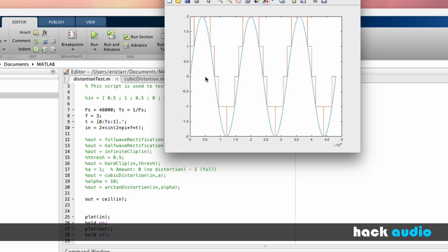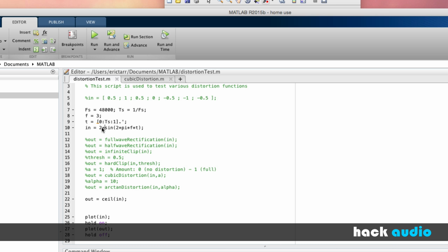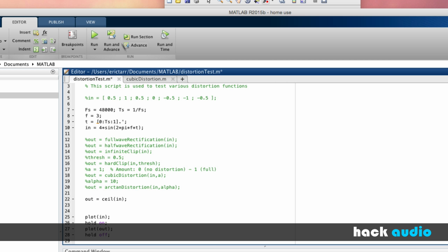Now, because we're working with signals that are stretched over a larger range, over a range of -2 up to +2, that's over 4 integers there, the number of bits is going to be 2. So we're stretching it out, and our amplitude scalar then is going to be 2 raised to the power of the number of bits minus 1. So if our number of bits is 2, 2 minus 1 is 1. 2 raised to the power of 1 is 2. Let's look at what happens if we go up to 4. What happens there?